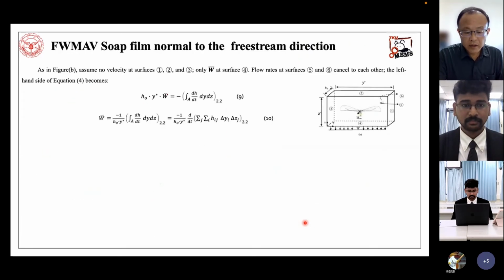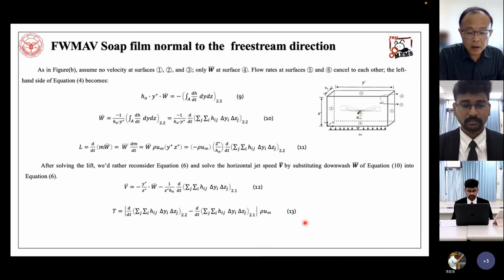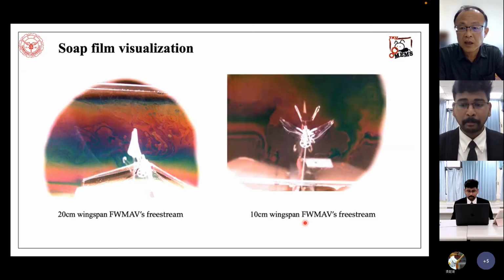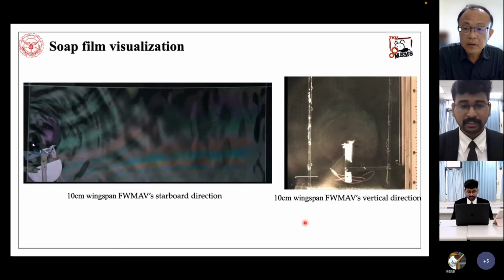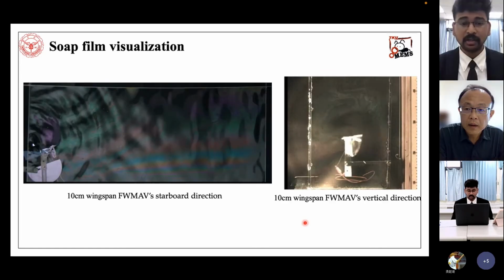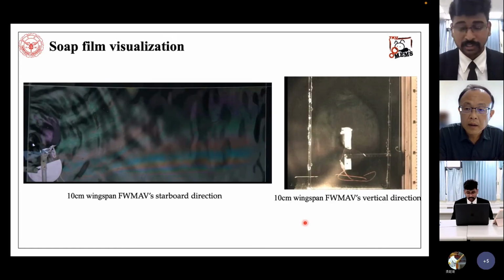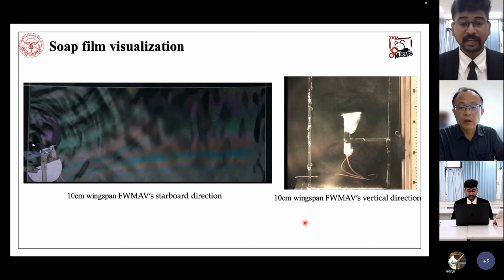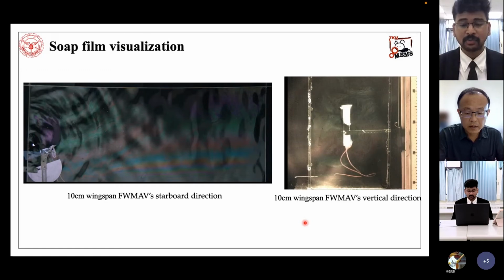And the values of the force for the wind tunnel test, how to get the force? Are there any sensors in the wind tunnel test, or is it also calculated from other formulas? Yes, professor. Actually, in the wind tunnel, we are using a 6-axis force gauge, a load cell. It is an experiment where we can directly get the lift and thrust values.